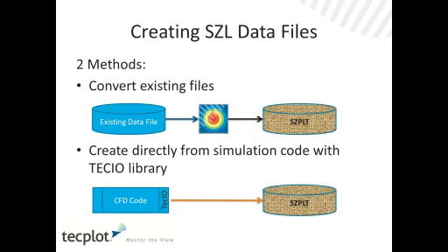So to create subzone loadable data files, we have two methods available to you. If you have existing data, your option is to use Tecplot 360EX itself as your converter. Load it into 360 and then have 360 write out your subzone data file.